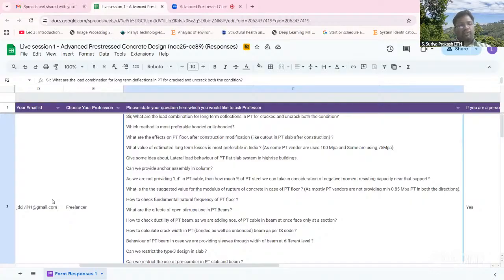In the bonded system, as you know, we have explained in the previous lectures, you achieve strain compatibility at every section. But in an unbonded system, your compatibility is achieved only in an overall sense, right? So the deformations in the strand and the entire concrete member have to be the same, or I should say, the stretching. But we don't satisfy the compatibility at every cross section. So from an efficiency point of view, from load resisting and the amount of reinforcement that you require, the bonded system will typically need less than an unbonded system.